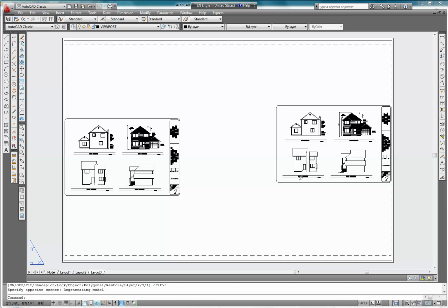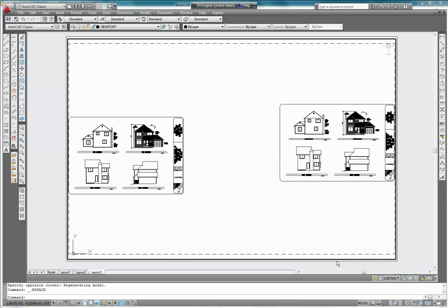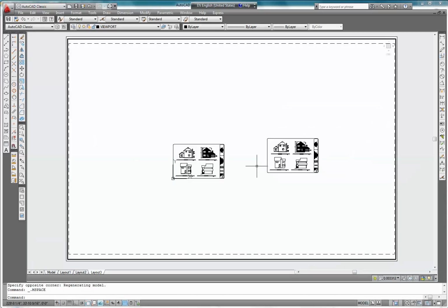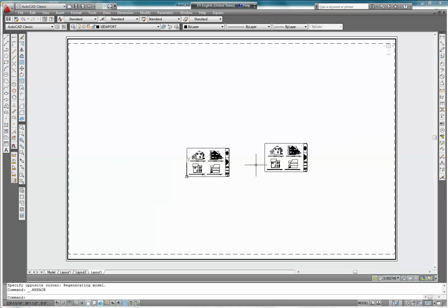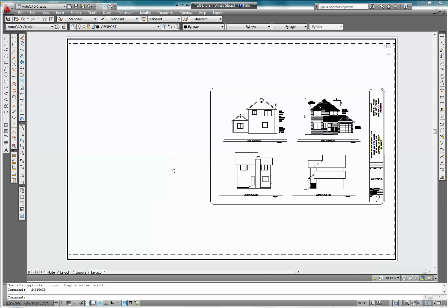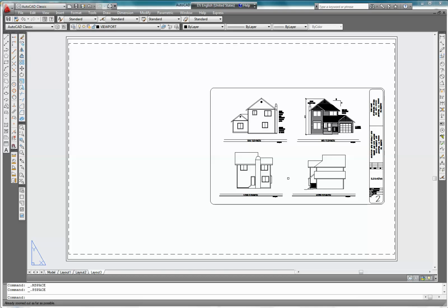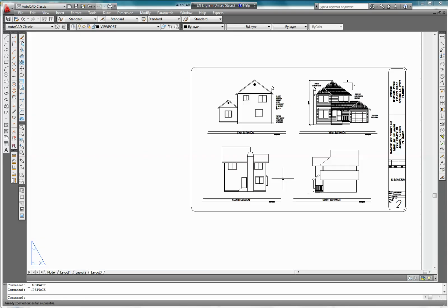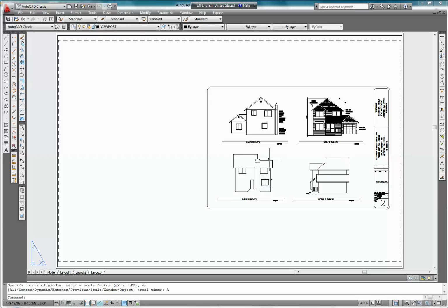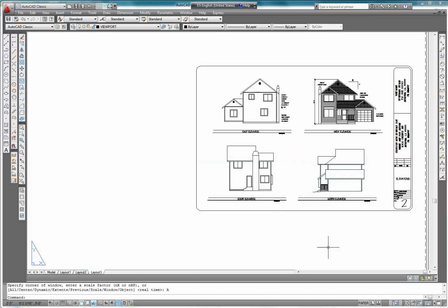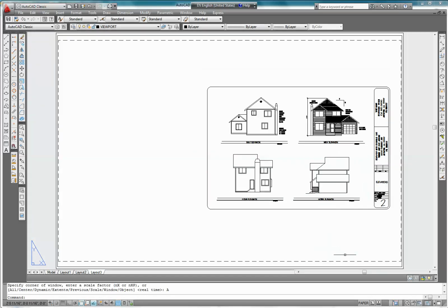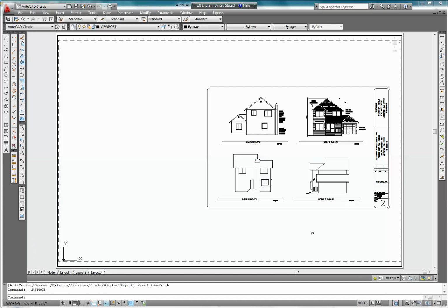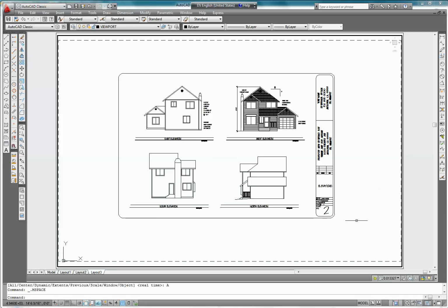Now take your drawing, first go to Model Space. In fact, you might want to mess around with that a little bit. Go to model space and then scroll in and out or pan around and see what happens. And then go to paper space and do the same thing. This isn't responding, so I'm going to go Z, enter, A, enter again. And you can see what the two different buttons do for you. Back in model space, put your drawing somewhere near the middle.